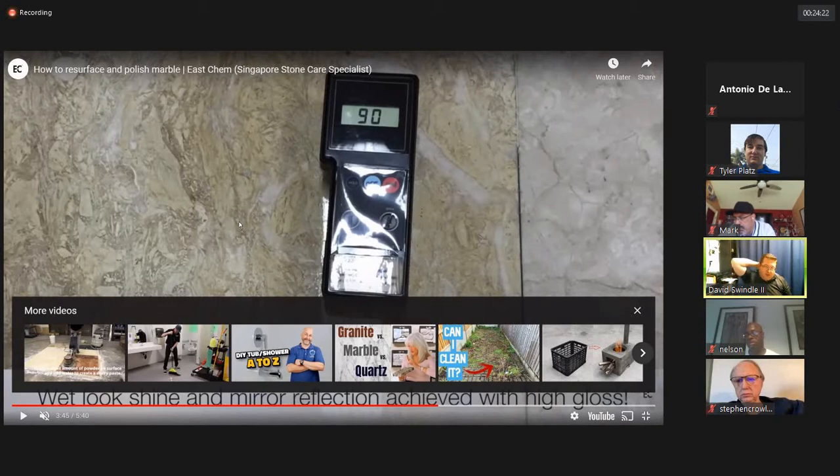I had a high-rise building in downtown San Francisco about 4 years ago that had granite floors, and they had dragged equipment and furniture across the granite floors. It was pretty heavy furniture that really did a number on the granite and left these scratch marks on it. We tried dealing with it, and we found that the soft diamonds, lots of passes over it, just being very slow with the process, worked best. We were able to get it out and restore the gloss. So it just takes time.